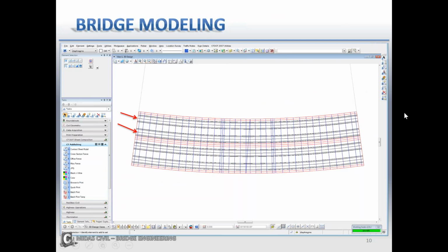Then I offset this baseline to all of my locations where the center of the girders would be, as you see in red here, which you can find this distance in the framing plan typically. I also offset the baseline to reflect the deck edges, basically the out to out, these two red lines here. Here you can see them, and here's all my center line for girders, this one, this one, this one, and this one. And I also use the radius of the bridge to generate the lines that represent where all the cross frames would be, as they are perpendicular along the curve.